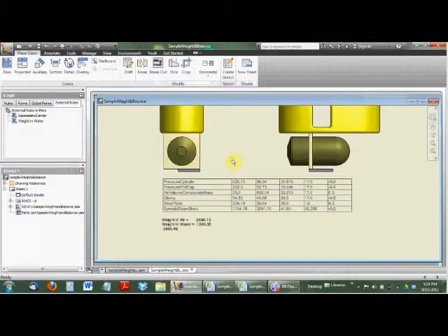Good. So now that's useful all unto itself, and that was actually my original goal. But I kept going with it, and I got some help from Autodesk to keep going with it, and I think this is wonderful. And it does need a little more testing than what I've done currently, but this is a great start. The other thing that you can do is you can generate a parts list that has your, in this case it's weight and air, displacement, X, Y, and Z for each of the parts relative to the origin in the assembly.